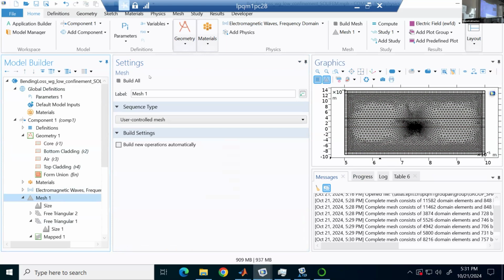Why did you choose 1.49? Because now the waveguide is even thinner. So you have more mode, basically your mode is all in oxide, not silicon. Silicon is 100 nanometer, so everywhere is oxide. The oxide refractive index is 1.5, so you would want it to be near 1.5.